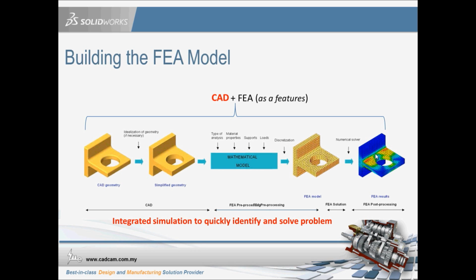As for the FEA, finite element analysis, we treat it as a feature inside SolidWorks, which means once you have your design done in SolidWorks, you can immediately mesh it and calculate the stress, deformation, or factor of safety results inside SolidWorks. Let's say you identify an issue and you would like to immediately improve the design.